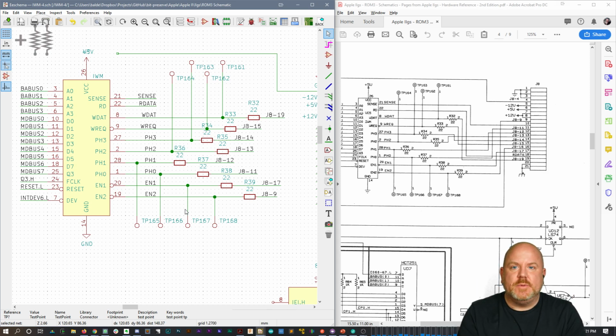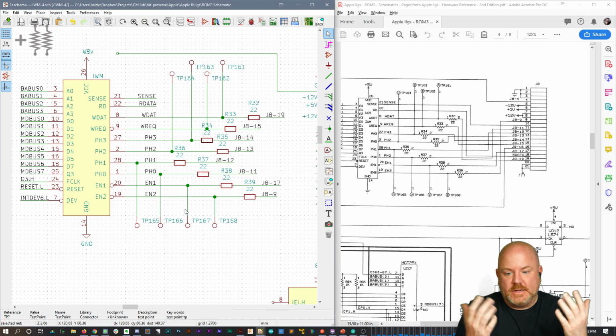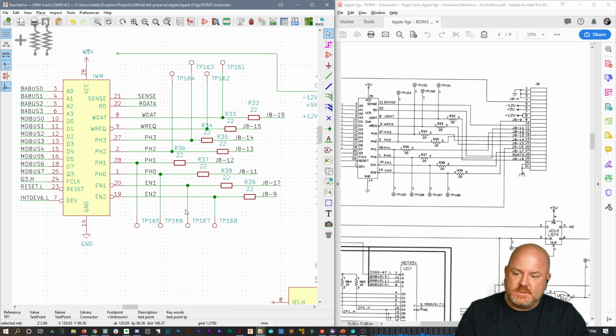He would connect his DMM and see that the pull-up was 3.295 volts, which is what he expected. But then he would connect the $8,000 probe and it would measure 2.78 volts or something. And so he was like, we've got to return it. You can't measure DC. This thing is crap. It's terrible.